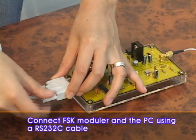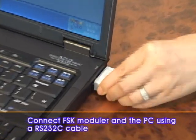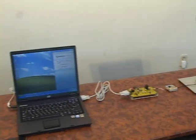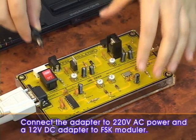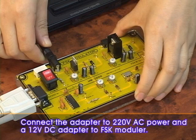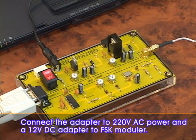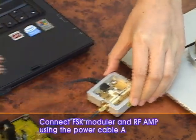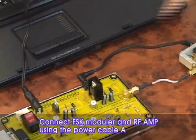Connect the FSK modular and the PC using an RS232C cable. Connect the adapter to 220-volt AC power and a 12-volt DC adapter to the FSK modular. Connect the FSK modular and RF amp using the power cable A.